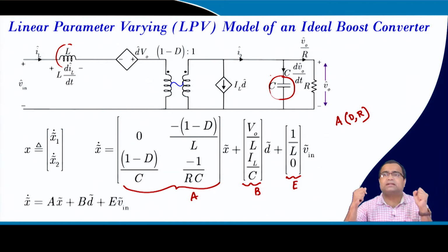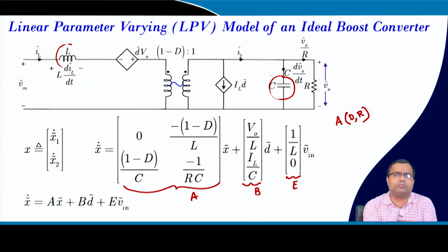So, this inductance may not behave like a constant value if we operate towards the saturation or the nonlinear region of the magnetic curve. But if we operate in the linear region, then the inductor will be more or less constant and the variation is not very significant. Same thing is for the capacitor. So, we are assuming the L and C variations are insignificant and those are fixed at the design stage.